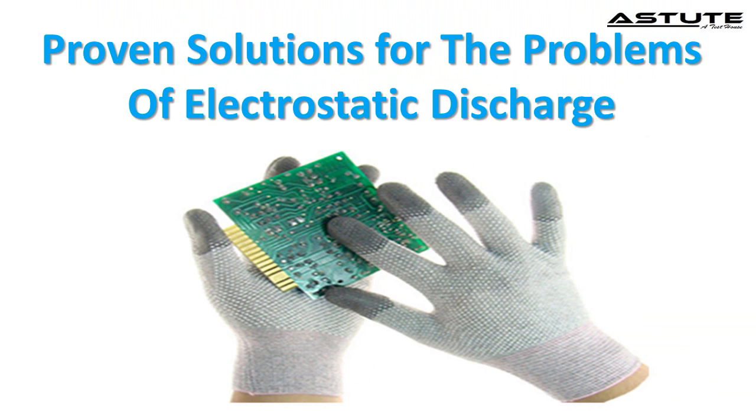For bypassing the ESD charge to ground or minimizing the ESD noise from the device, the following tricks are very important. Keep all synthetic materials at least 4 inches away from electronic equipment. When cleaning printed circuit boards, use a spray labeled as non-static forming. When troubleshooting electronic equipment, always wear a static wrist strap that's grounded to the frame of the device. Also, wear the wrist strap when handling printed circuit boards. Treat carpets and floors with compounds that reduce the buildup of static charges. Use static floor mats where necessary.